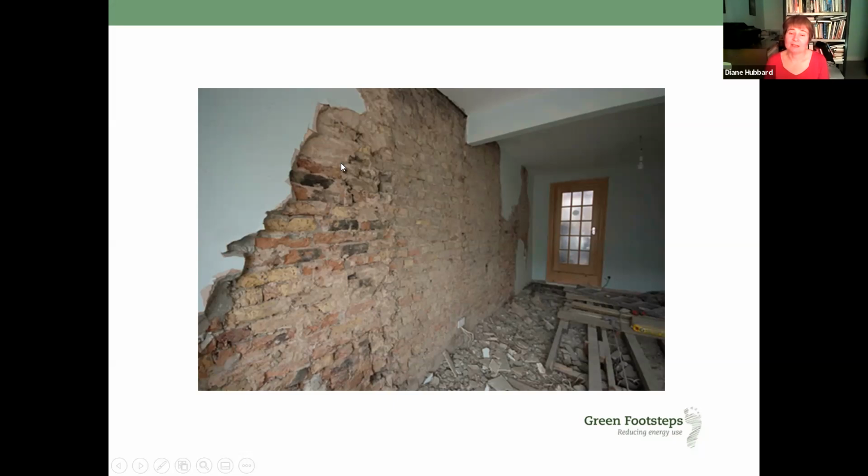What's happening in the void between a ceiling and the floor above, where the joists go into the wall. What's happening where it's coming up through the floor. So think about those areas. A fundamental thing is to think about those areas where you haven't got plaster actually on the wall.